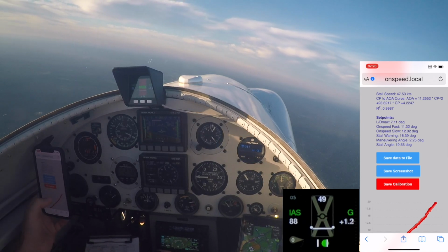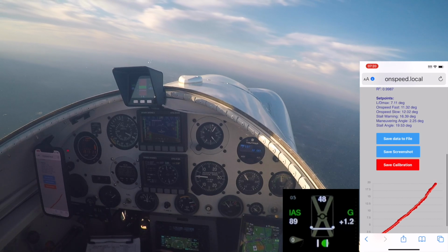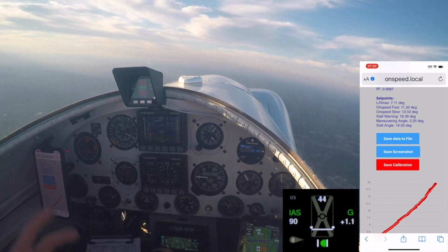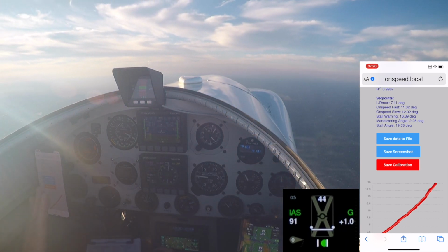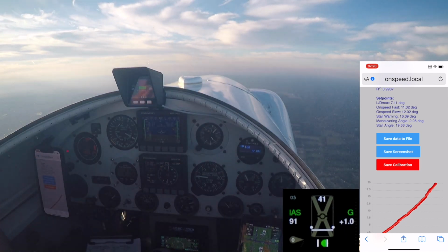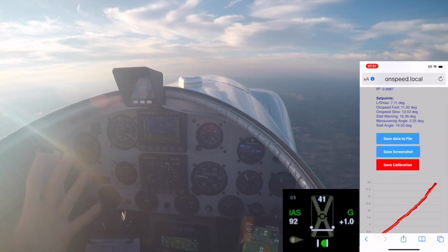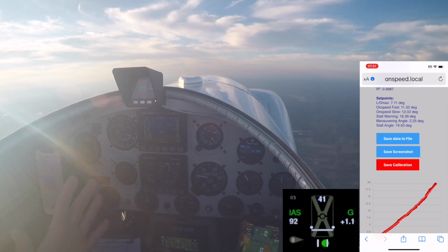And then it computes the different body angles associated with my primary conditions. So I've got an LRD max body angle of 7.11 degrees. The on-speed band is going to go from 11.32 to 12.02 degrees. I like to tell people it's about 1 degree wide, but it's going to vary anywhere from about 0.6 degrees to 1.0 degrees, depending on the calibration and the airspeed band of the airplane.